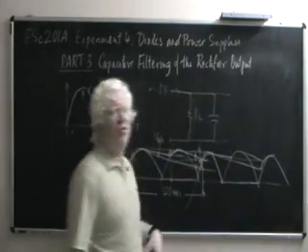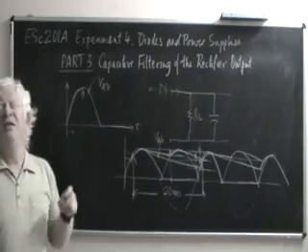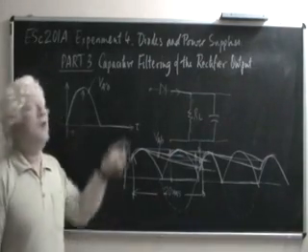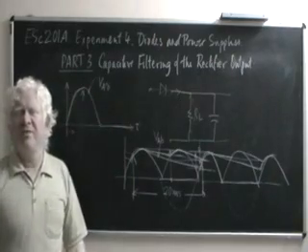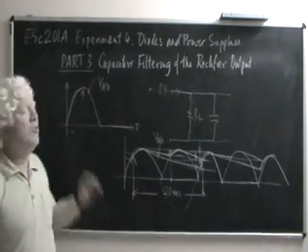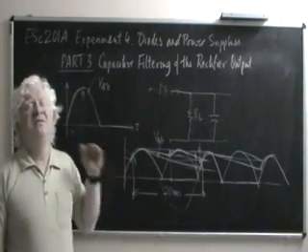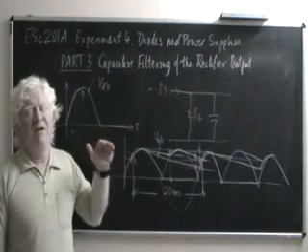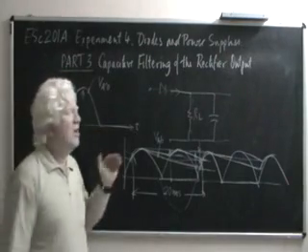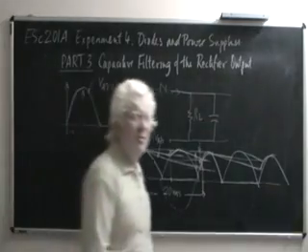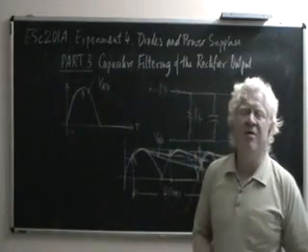A far more level waveform than what you would get with the same capacitor, same resistor, if you had a half wave rectifier. A full wave rectifier is giving you a far more constant output, an output with much less time variation. So clearly a full wave rectifier scores over a half wave rectifier in this respect, and that's why we use a full wave rectifier.